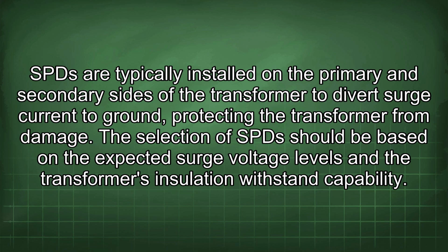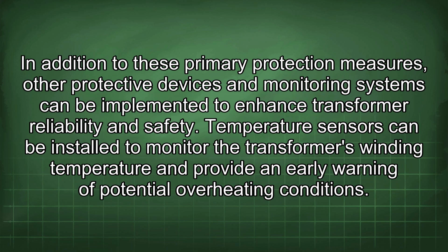SPDs are typically installed on the primary and secondary sides of the transformer to divert surge current to ground, protecting the transformer from damage. The selection of SPDs should be based on the expected surge voltage levels and the transformer's insulation withstand capability. In addition to these primary protection measures, other protective devices and monitoring systems can be implemented to enhance transformer reliability and safety.